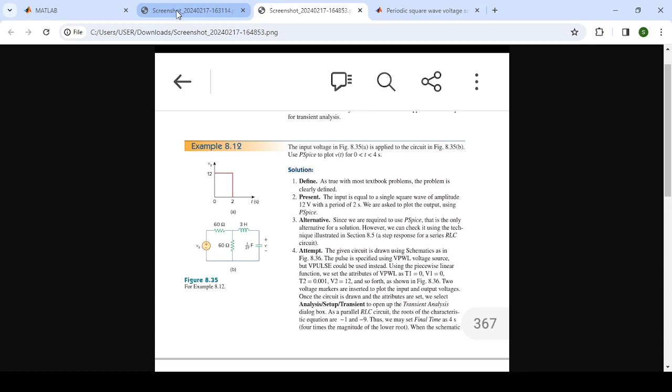between the time I made the last video, I came across a particular problem involving that technique of using a pulse generator to control a switch to create a voltage pulse. And that problem was that whenever your voltage drops to zero, that's the equivalent of a short circuit, not an open circuit.